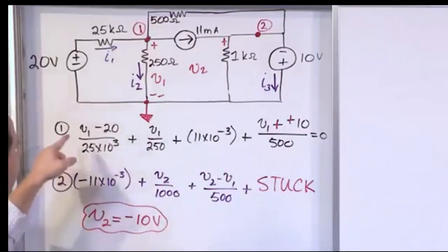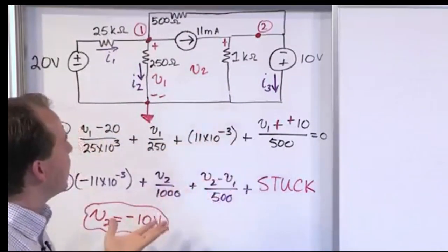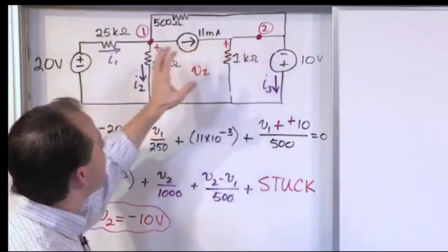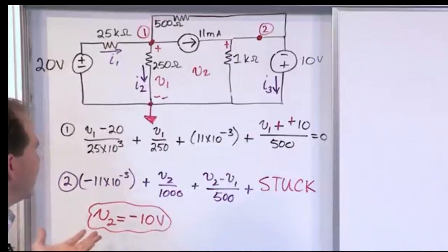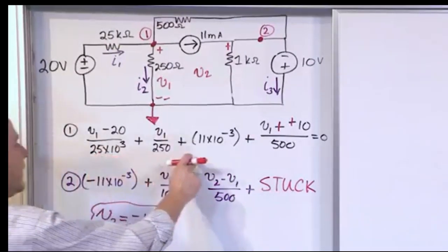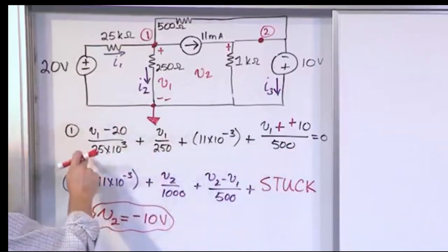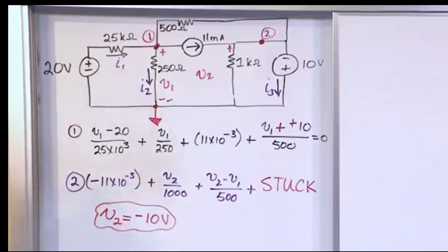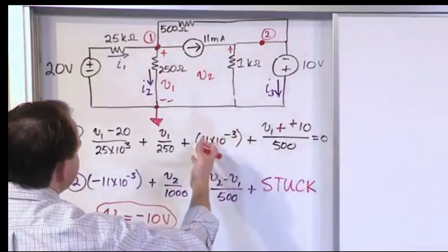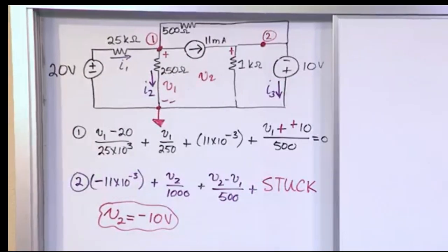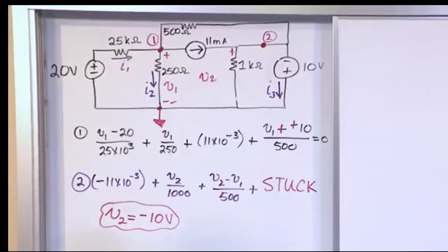This one's different. It doesn't actually involve anything except for V1, and it's that way basically because of this over here and the way everything's constructed to set this up for you. So actually, you could just solve this equation by the rules of algebra and calculate V1, and then you would have V1 and you already know V2. Bam, the rest of the problem can be solved. Once you know the node voltages, you know everything. So that is what we want to do.